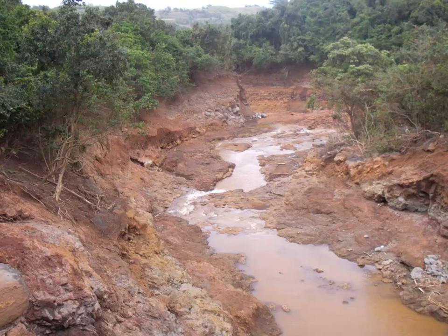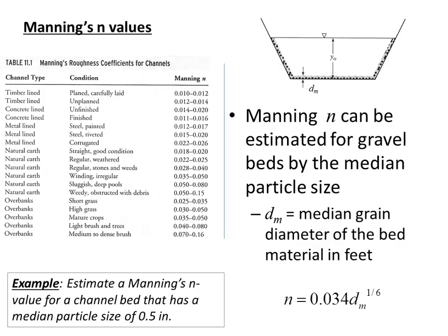And so there's going to be a roughness there that depends on more than just what it's made out of at the molecular level, but it has to do also with how jagged the soil is. And so we'll come back to this picture and talk about some additional things related to it, but I just wanted to point out that even for a material that you maybe would consider smooth by itself, like some clay, when you make an entire channel out of it, just the way that it collapses and breaks apart is going to have a different resistance than the individual grains that it's made out of.